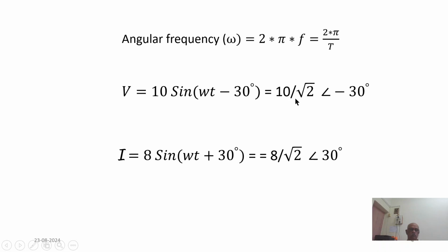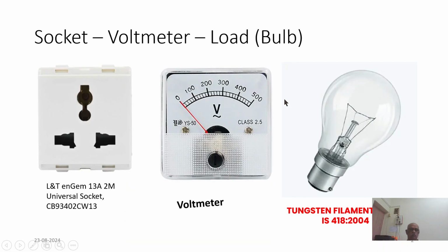So for example, let's say somebody says, hello, that means he's trying to draw attention. So that's a symbol. Similarly, we are creating a symbol for this equation by this. It's nothing beyond those symbols. Following the same way, we can see the amplitude is divided by root 2, that is, we are getting the RMS value. But why are we taking RMS? This is what we measure. You remember that we have got a voltmeter. This voltmeter is actually measuring the RMS value.